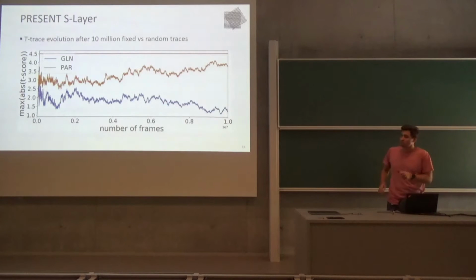significantly less leakage. But if you actually place and route the design and you get all the asymmetries, the leakage is getting considerably higher. Now, this could have been run for longer, but one of the points here is that this is a design methodology which should provide a certain confidence. We cannot say that in the end this will be secure because it isn't leaking, because we know that as you start manufacturing, process variations and other things can increase the leakage and decrease the security.